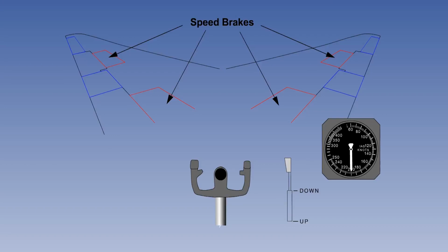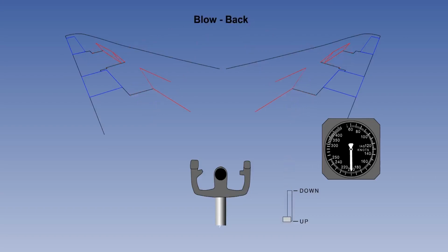There is a speed brake lever on the flight deck that, when selected to up by the pilot, extends the speed brake symmetrically, thus increasing the drag. There are no speed restrictions for the operation of speed brakes. However, the design of the hydraulic operating system does give a blowback facility. That is, for the same selection from the flight deck, increasing IAS restricts the speed brake angle of deflection into the airflow. This prevents excessive buffeting at higher IAS.